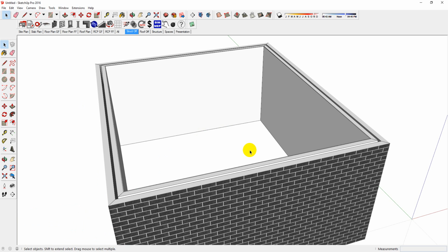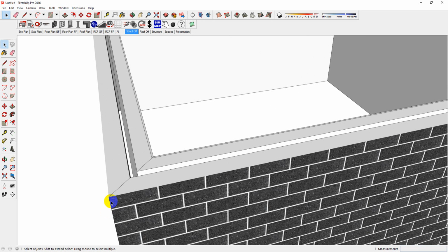with Plusspec you can automatically generate slabs and joists from your walls, as long as your walls form an enclosed loop. For your walls to form an enclosed loop, each corner needs to have the miter symbol. The miter symbol does not actually mean that your walls will be constructed with a miter. It simply shows you that in Plusspec they're recognized as being joined.